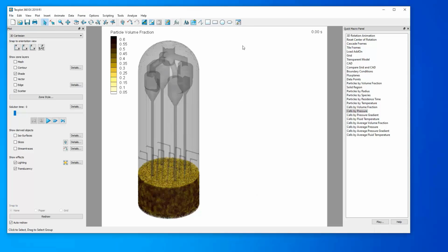And now, we're going to want to select this frame, which again can be done using the Selection tool and clicking towards the boundary. We'll know it's selected by the 9 black dots around the perimeter of the frame. Now, we'll hit Control-C to copy, and Control-V as many times as we want additional frames. We'll press it twice now to create 3 frames.